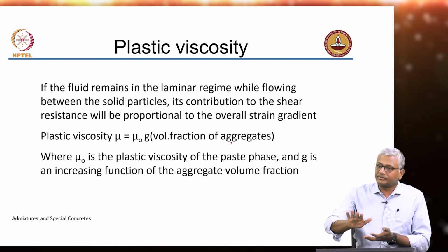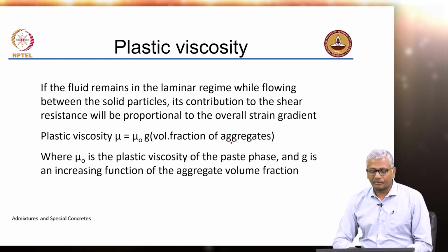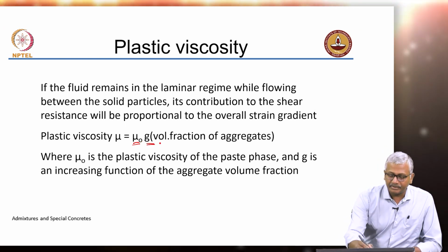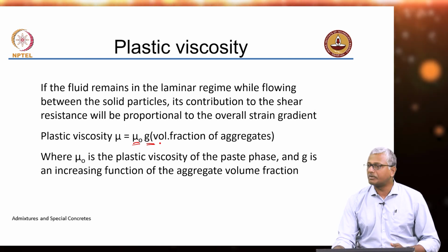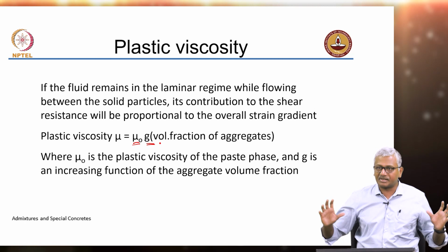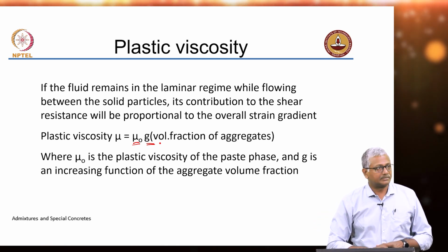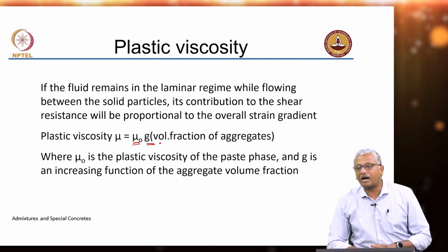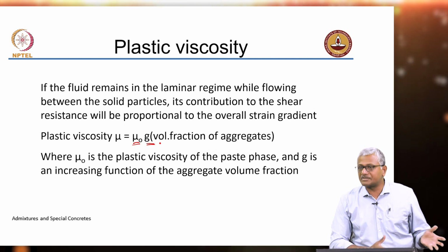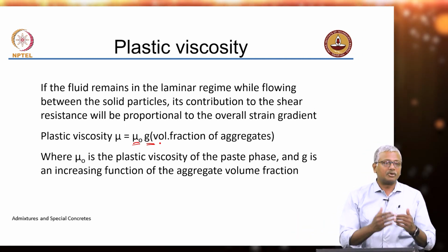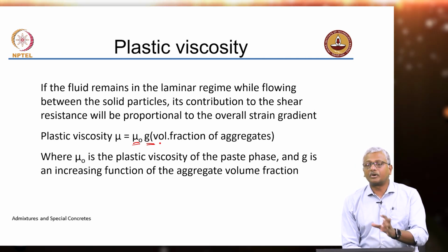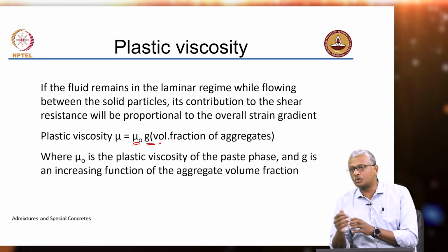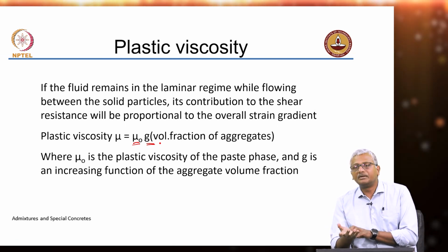Viscosity: once the flow happens, what is the resistance to this flow? That is defined by viscosity. So, viscosity of concrete is a function of viscosity of paste and a function of the volume fraction of aggregates. Again, why? Because if you have a lot of aggregate, even if the paste is less viscous, it needs to carry this aggregate along with it, right? So, if you have more aggregate, the viscosity will become higher for the concrete. So, if you reduce the volume of aggregate, you get a lower overall concrete viscosity. Okay. So, all this has to be looked at carefully when you do the mix design for different types of applications. You may need different approaches for different applications.